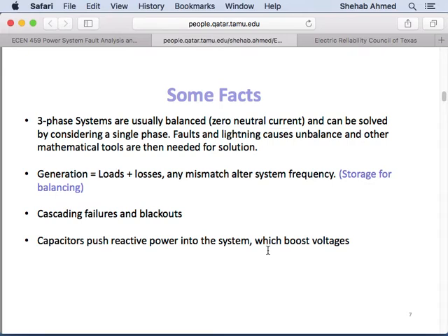You break down the air, but how do you sustain the arc? The arc is nothing but current flow, and the length of the arc is an impedance to the current flow, right? So they bring the two electrodes close to each other, create the arc, and then they start stretching it a little bit, moving it around to melt all the metal that they have. So they're creating short circuits intentionally.